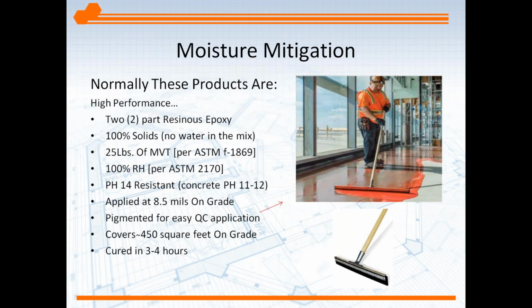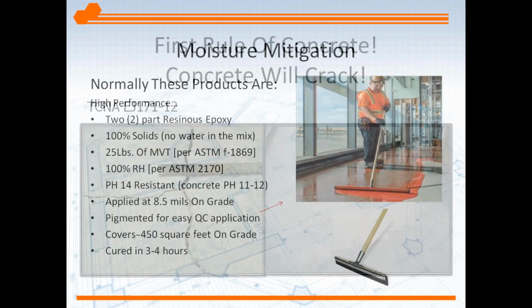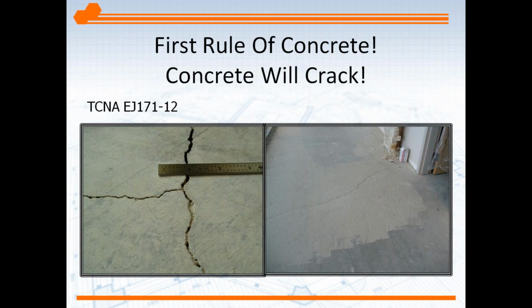It's just the vapor is too high, or possibly they don't have time to worry about that. They're on a fast track. So instead of testing the concrete or helping the concrete dry out, they're going to go ahead and moisture mitigate, they're going to self-level, and they're going to install the flooring. Again, another topic we could talk quite a bit about offline.